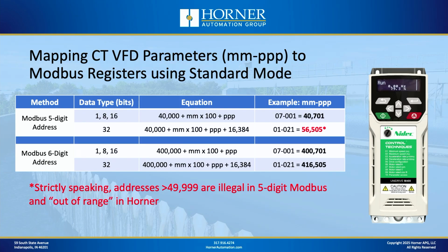All right, now let's talk about mapping drive parameters, your menu number and your parameter number, to Modbus registers. I mentioned that there's a mathematical relationship that you can use, and that I really like, and that's absolutely true. So let's go through that. First of all, just to review what I said earlier, all the data available in the drive is in integer form.